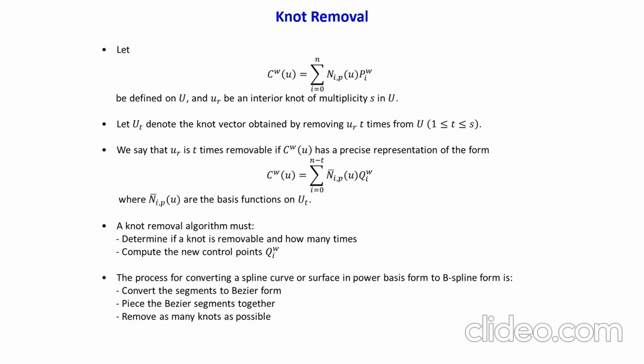Other uses of knot insertion, and therefore their eventual removal, include increasing the number of control points in order to interactively shape a B-spline curve, and linking B-spline curves together to form composite curves.